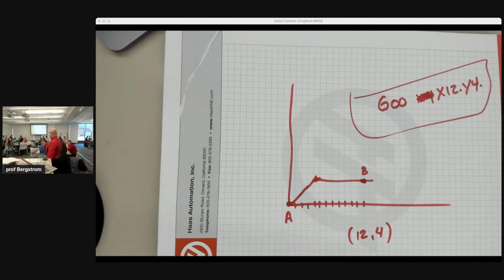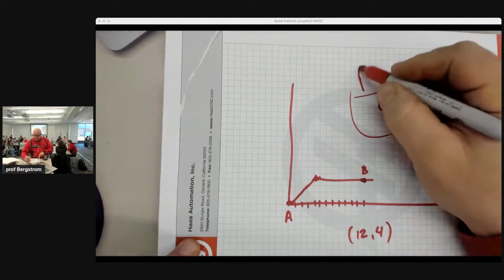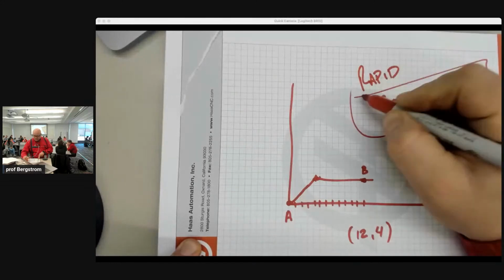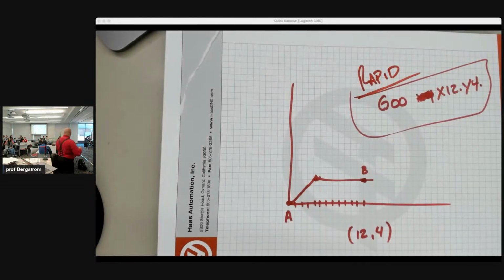And so it'll move in a diagonal line until it gets to the Y value that's correct. So as it gets to the Y value that's correct, it'll turn off the Y motor. It'll just move the X. So that's rapid. And so that's that 50, 100% rapid. That's what we're controlling when it's a rapid motion. We program rapid motions when we're not expecting to cut the material.